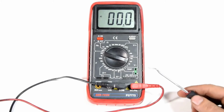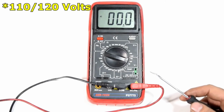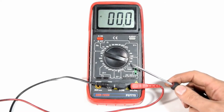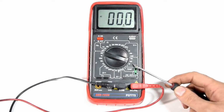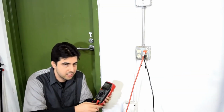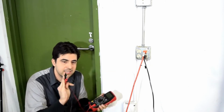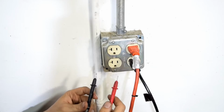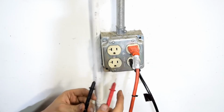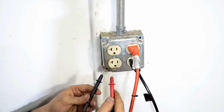So next we're going to see whether we have current at a wall socket or not. Since we get about 110 volts here in the States, we're going to set our dial to 200, which is the next one up from the voltage we're expecting to measure. Alright, a word of caution: when measuring high voltage like this, you need to be 100% sure of the integrity of your multimeter, plus the wires that go to your test leads and the test leads themselves.